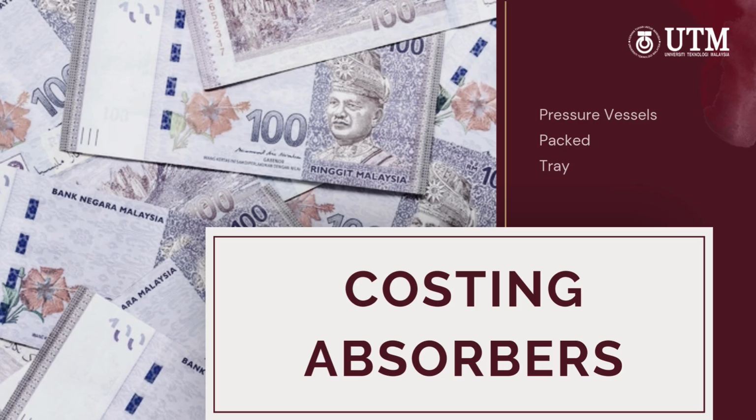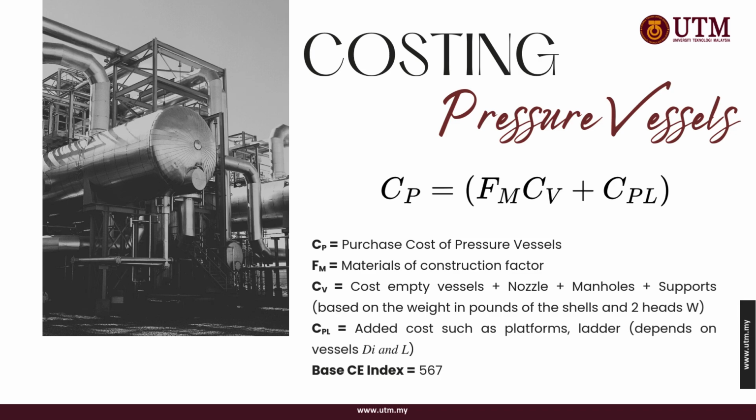Okay, the next one we will discuss is the cost estimation involved in an absorber. The main focus here is to understand the calculations and formulas required for accurate costing of pressure vessels, packing and also trays, which are very critical components in the chemical industry. Let's start with the formula used to calculate the purchase cost of pressure vessels, denoted by Cp. The formula is as follows: Cp equals FM Cv plus Cpl.